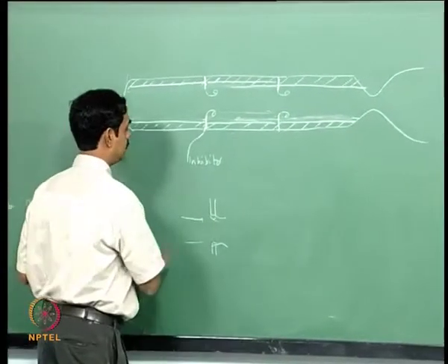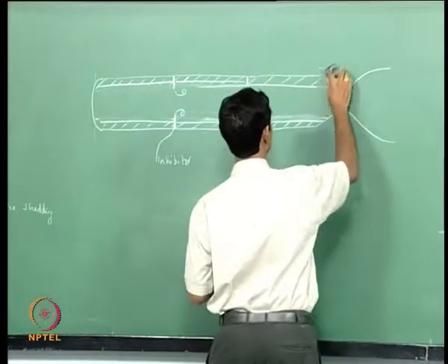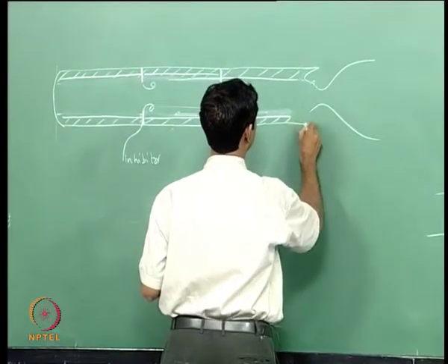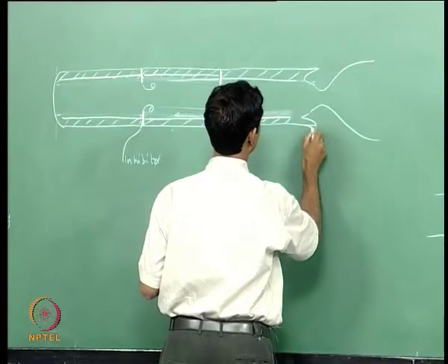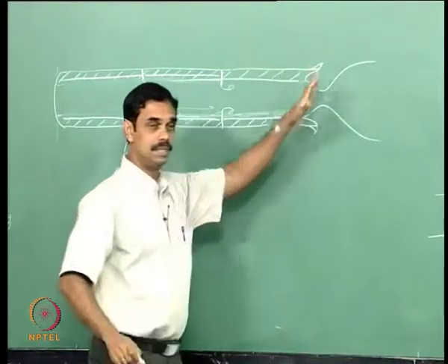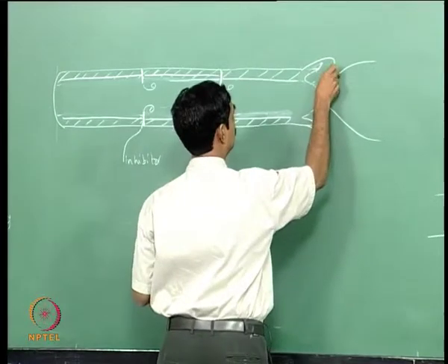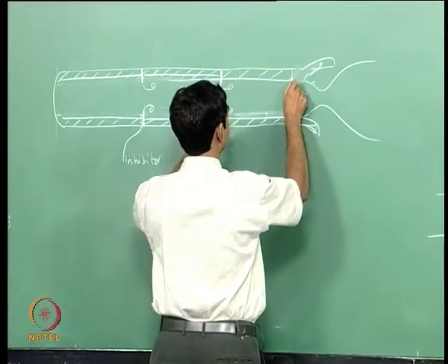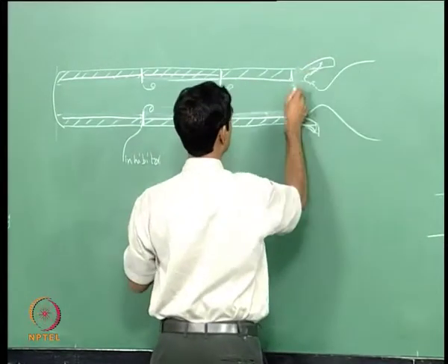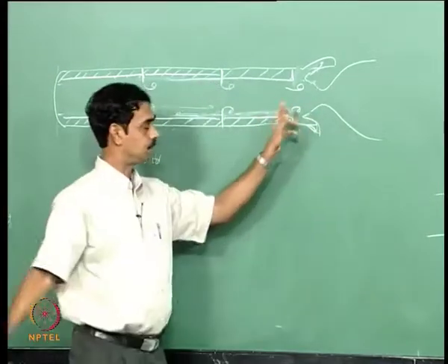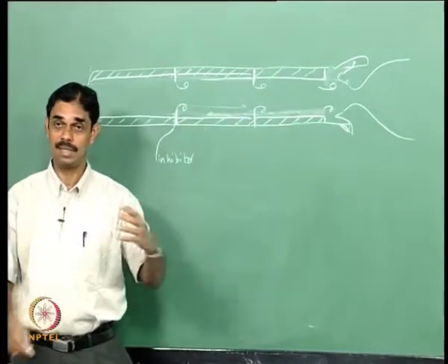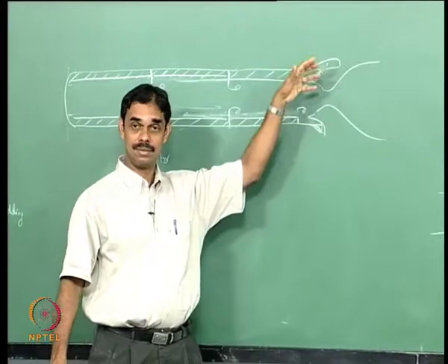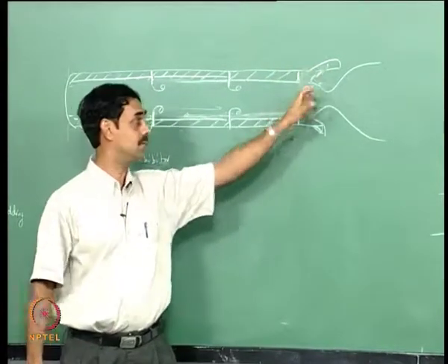And yet another possibility is, if you have a nozzle which has a bucket-like structure, because of the gimballing mechanism there will be some space provided here. So this is where the gimballing mechanism is, and the vortex will travel over this cavity, and it is like my blowing over the bottle. This works like a Helmholtz resonator, and it creates the sound here as the vortex goes over this.